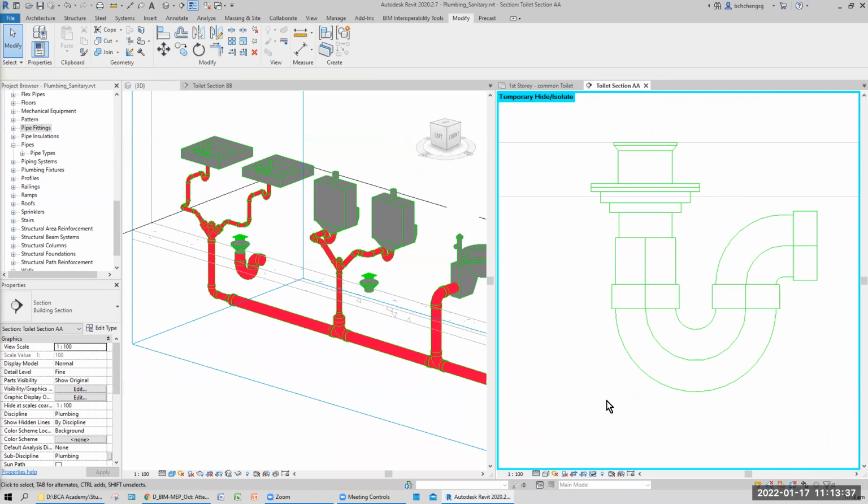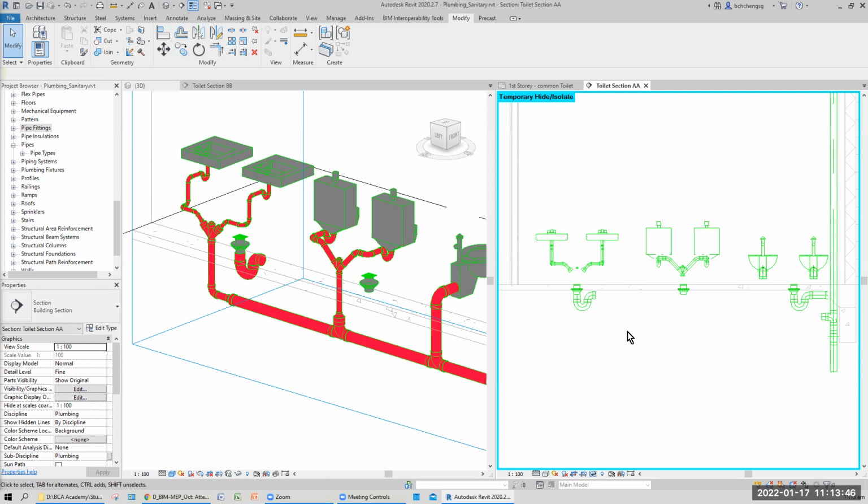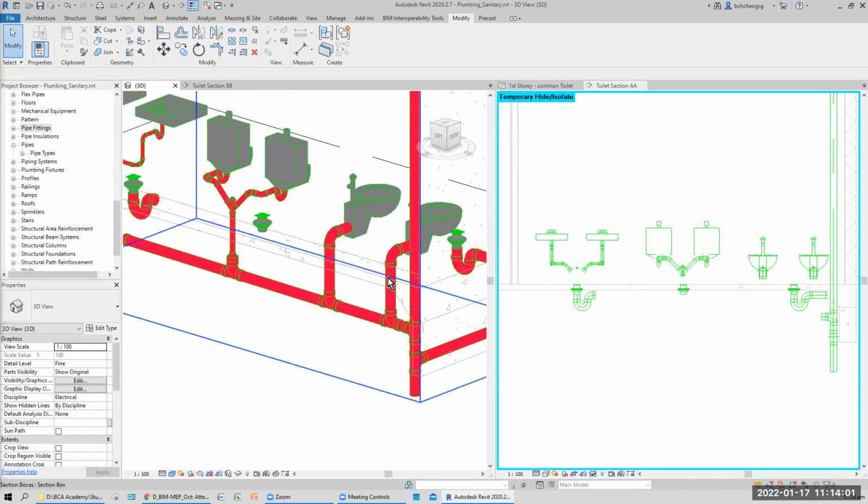Okay. The next step, not just to copy this to this, is to draw the actual pipe connected to there. All right. So pipe connected to there, you can actually draw from here. Now, this is a sloping pipe, correct? So you can actually draw the sloping percent if you want. All right, if you don't want, you draw a straight pipe, is still okay, seriously. Because this pipe is big enough, it's 100 mm in diameter.